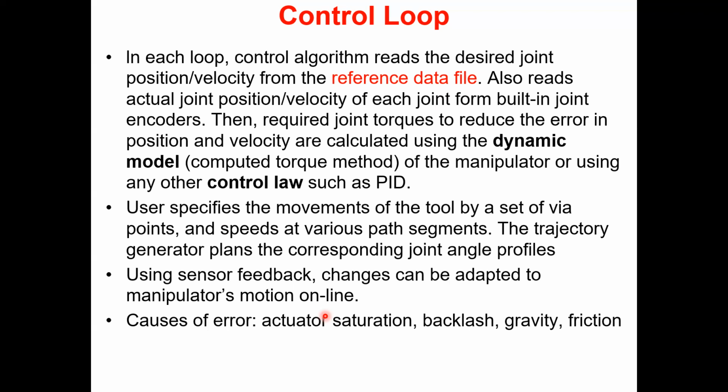Usually when you plan trajectories for manipulators, you need to know the capability of the actuators, right? What is the motor attached to joint 1? What is the motor attached to joint 2? What are their capabilities? How much can they turn in 1 second or 100 milliseconds? You should not make a trajectory which asks the servo controller to rotate that joint beyond what is maximally possible.